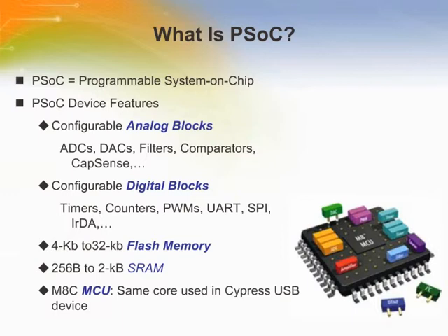PSoC stands for Programmable System on Chip. PSoC is a device that has an array of hardware blocks that can be configured to perform a variety of functions. The analog blocks can be configured as analog to digital converters, digital to analog converters, filters, and even capacitive sensors. We'll discuss implementation of capacitive sensors a little later.